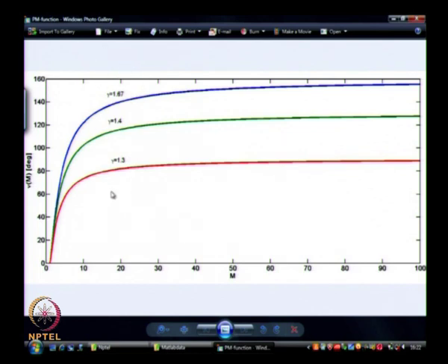As usual we always want to discuss compressibility. We said that changing the gamma is one way of changing the compressibility effects. That is not the only way to change compressibility, this is just one of the ways. I am going to say that gamma equal to 1.67 is least compressible, and as I go more and more it is becoming more and more compressible, that is what I am having here. When gamma goes from 1.67 to 1.4, gamma decreases, compressibility increases.